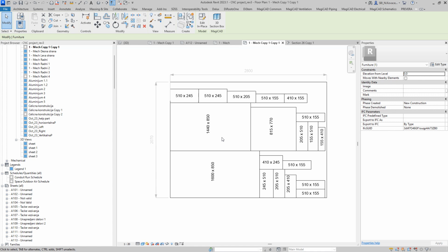Because at the end in assembly I need correct dimensions. This is just to check that everything can fit. So if you are using this for a similar case, it is okay as a first iteration to use the offset, but if you need to send this to some supplier, please make sure that you use correct dimensions.